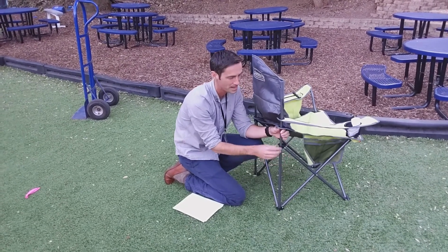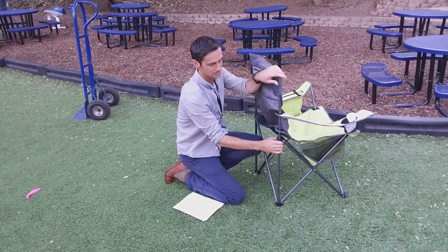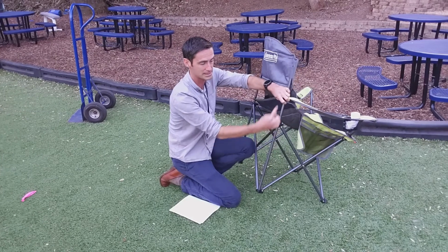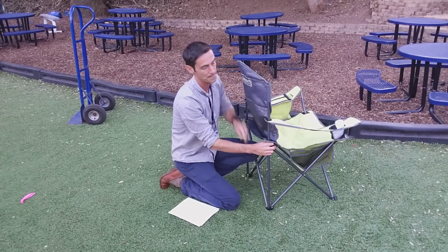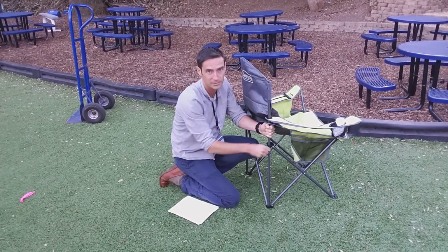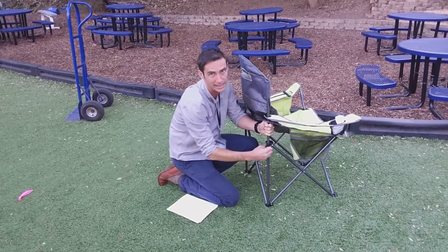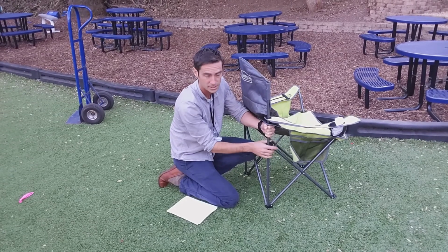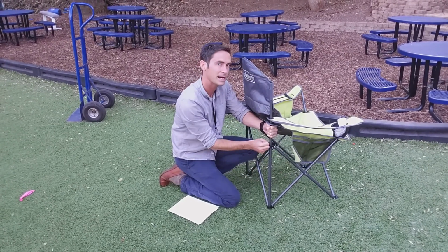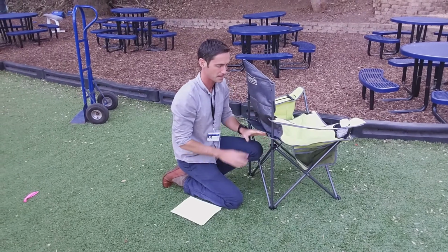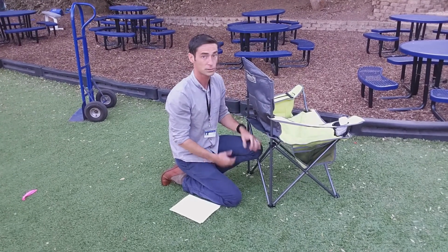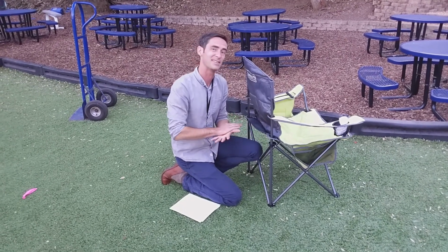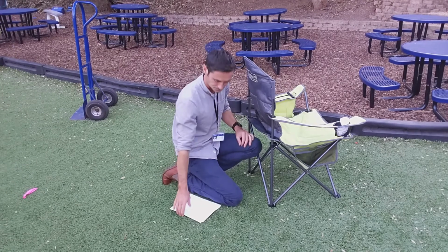Can you imagine that? It also clearly has one translational degree of freedom. It slides up and down the shaft, but it cannot slide out in the X, out in the Y. It can only move up and down in the Z, okay? And it can rotate in one direction if we were to cut it loose, but it can't rotate the other 2 directions. So this one has 2 degrees of freedom. 1 translational, 1 rotational, and the other 4 are constrained.